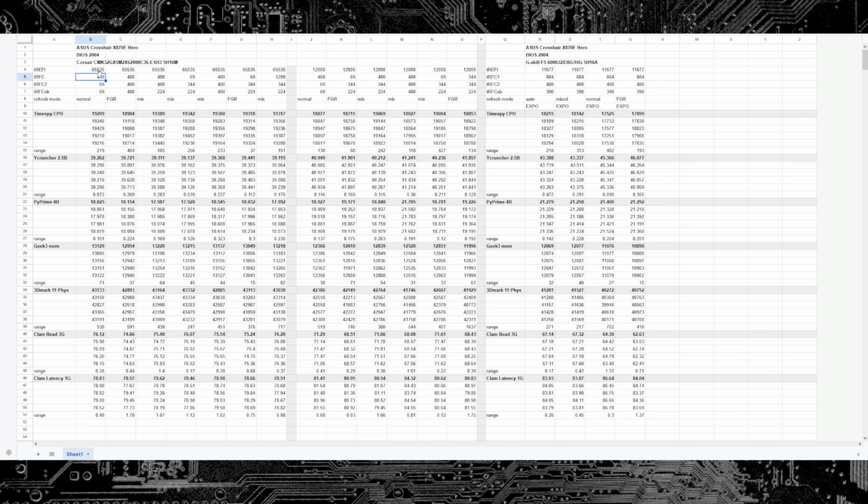Also, I think with multi-rank setups, there might be slightly different performance behavior. Like in dual rank, normal mode might... Well, I'm not sure. I tried checking the documentation, but I didn't spend enough time searching through it to find the definitive answer. But I think that in normal mode, when a refresh command is sent, it actually refreshes all of the memory ranks, not just one memory rank. But I'm not 100% certain about that. I think for DDR4 it worked that way.